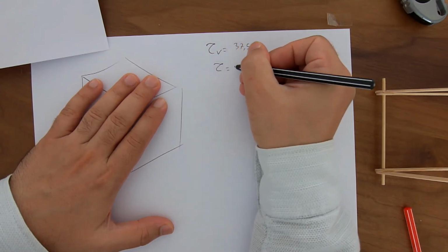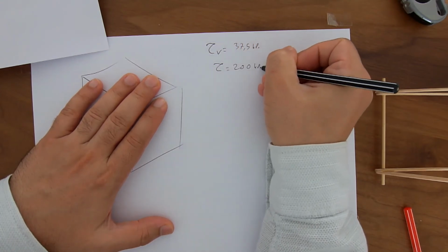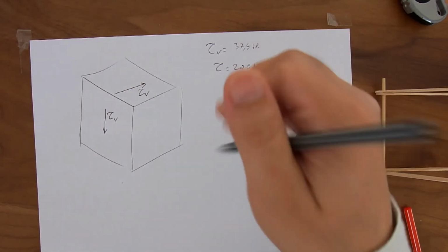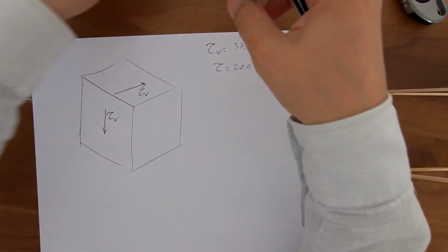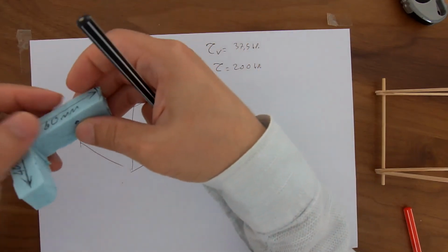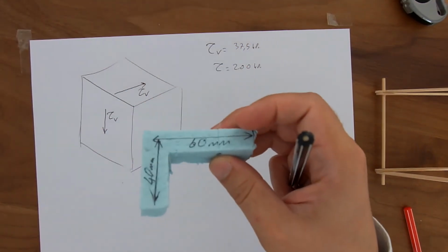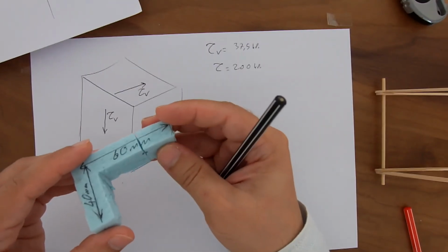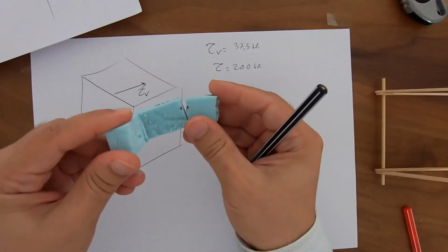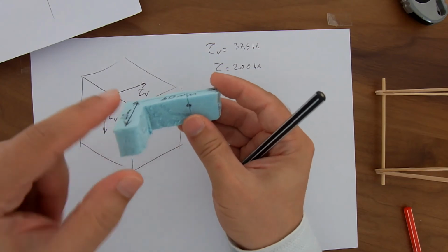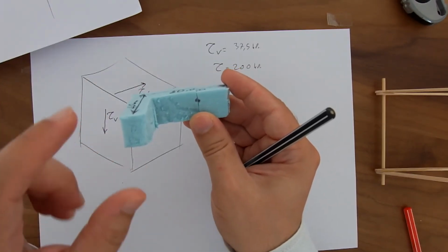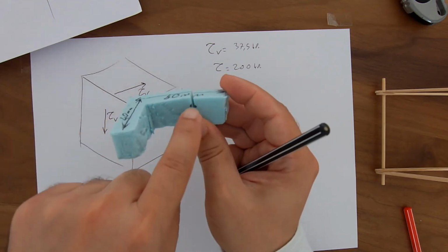We found bending stress 200 kilopascal. And where does it act? The bending stress. So where is the piece? Okay. Here you see this was the bending. So that means at this point, which is above the neutral axis, there is tension.